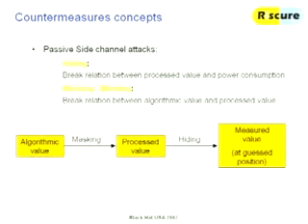So basically, you can see it like this. You have an algorithmic value, like, okay, I'm doing a DES with this key, then I have to do this kind of operation. By changing the algorithm by using a random value, for instance, to mask it in, you change the value that the actual XOR instruction is processing. So the power consumption is also related to that new processed value, making it difficult for an attacker to know. And then you hide it. You try to make it very difficult for an attacker to know when this value is being processed.